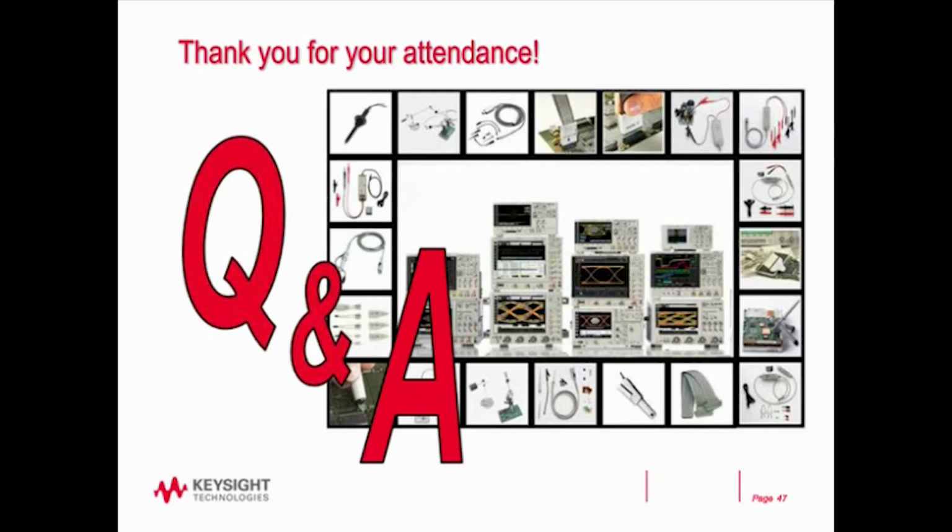What are the low and high frequency step points for the PSRR sweep? I believe the low point is 10 hertz. The highest frequency is 20 megahertz. That's the maximum bandwidth of the built-in generator on these scopes.